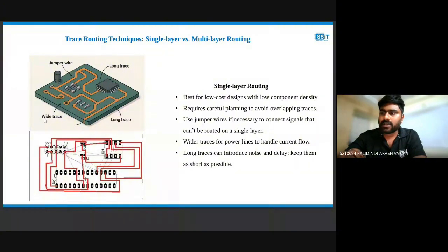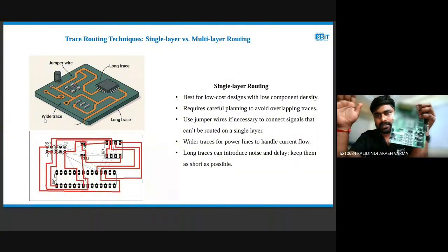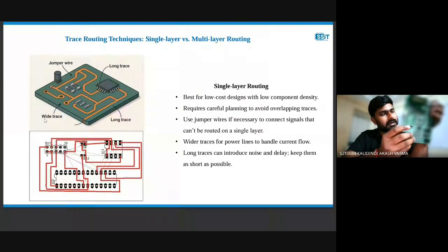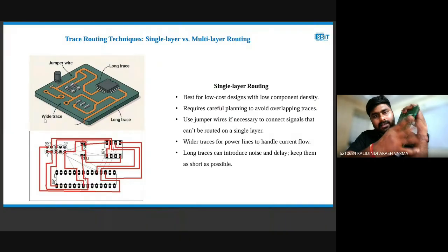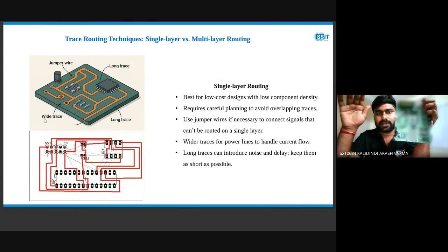Obviously, because we should not go for increasing the PCB size. If there are components on the back side, bottom side, and top side, we could place all of them on a single side, but then the size of the PCB will be increased, which is unwanted.